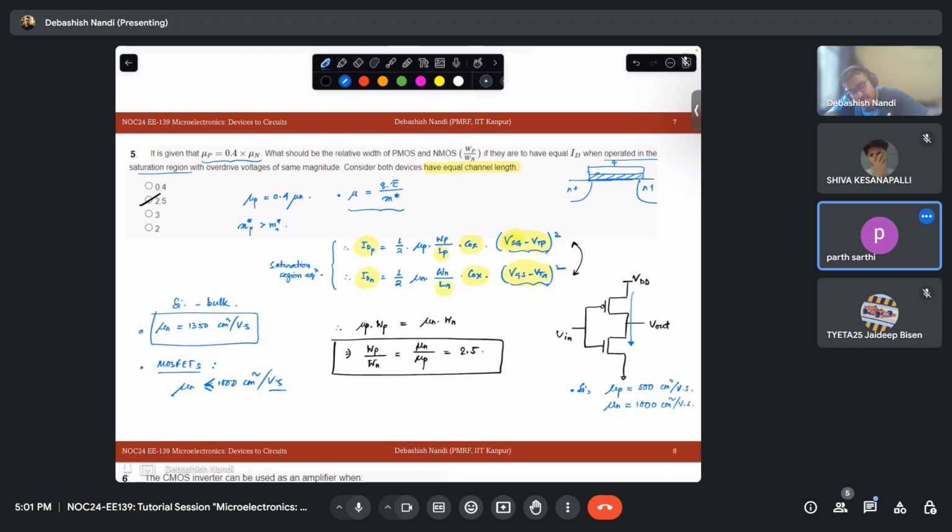So it is basically two materials, SiO2 and silicon. This surface will have roughness. What do we mean by roughness? Roughness means there will be dangling bonds, unfulfilled silicon bonds. There will be a region where it is SiOx, and x will lie from 0 to 2, and then it will have SiO2.